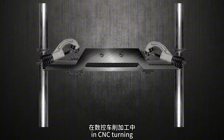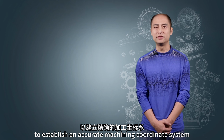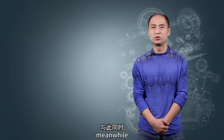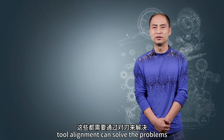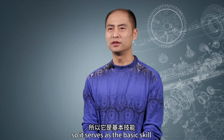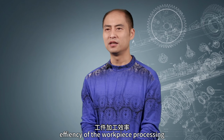In CNC turning, we should first determine the machining origin of the part to establish an accurate machining coordinate system. It's crucial for CNC operation. Meanwhile, we also need to consider the impact of different tool sizes on machining. Tool alignment can solve these problems. So, it serves as the basic skill and the foundation of efficient workpiece processing.